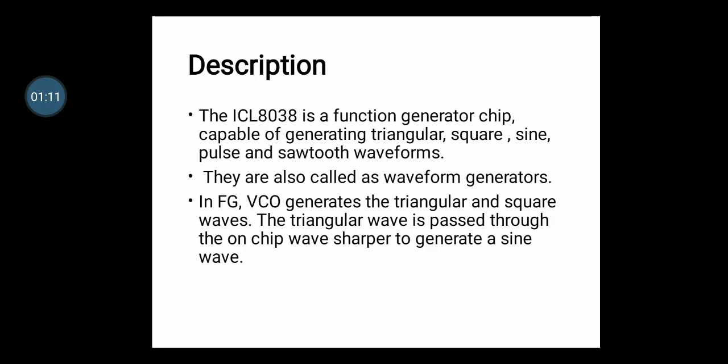Before going into this circuit diagram, let us see what a function generator actually is and how it works. As already told, function generators are designed to provide the basic waveforms such as square wave, triangle wave and sine wave. They are also called waveform generators. The monolithic function generator provides these basic waveforms with a minimum number of external components, reducing complexity but increasing the reliability of the circuit. They find application in communication, telemetry, electronic music, and testing and calibration in the laboratory.